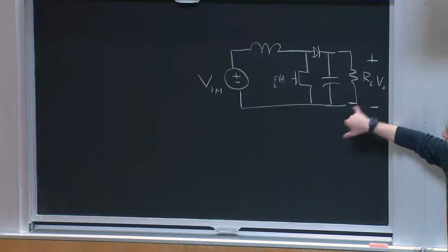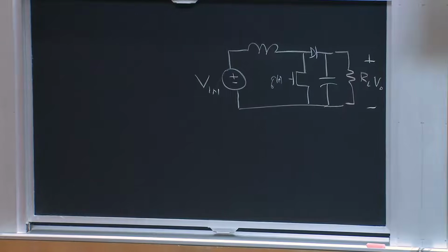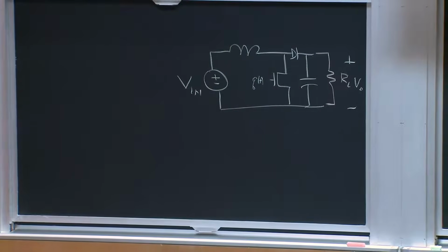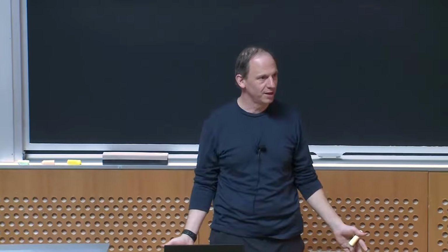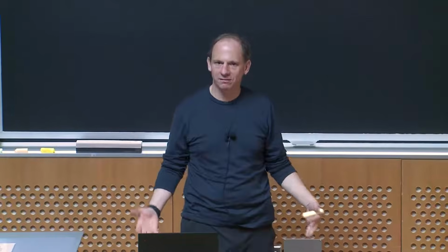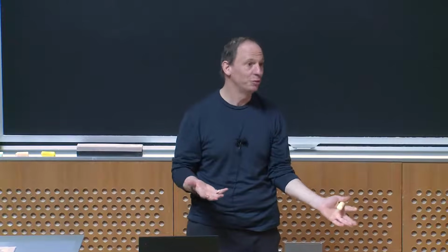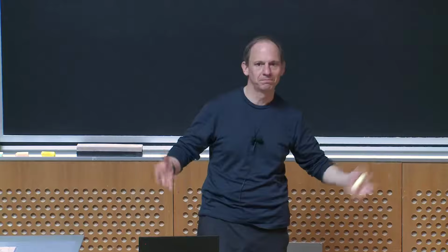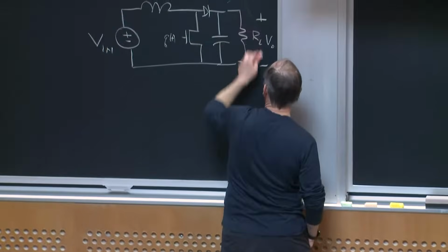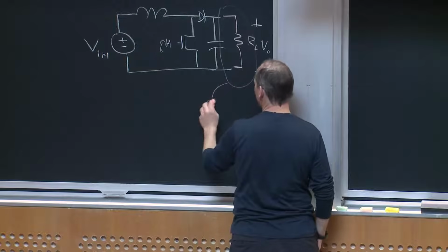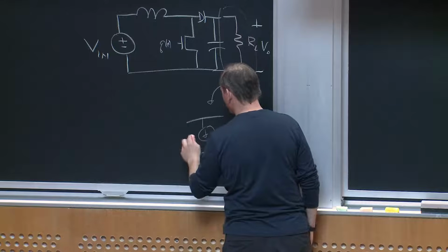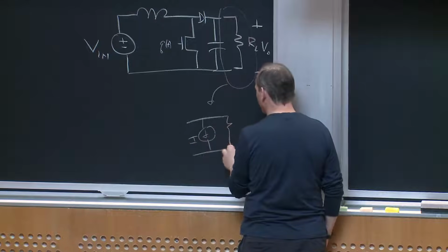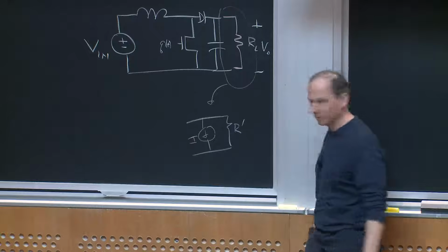Now, just by way of an aside, in my examples I usually show a resistive load. A lot of loads are resistive, right? But there's no guarantee that, in an actual application, your load looks like a resistor. It could look like whatever. Maybe a lot of loads you might represent as some Norton equivalent, where there's some constant current component and some resistive current component, right?